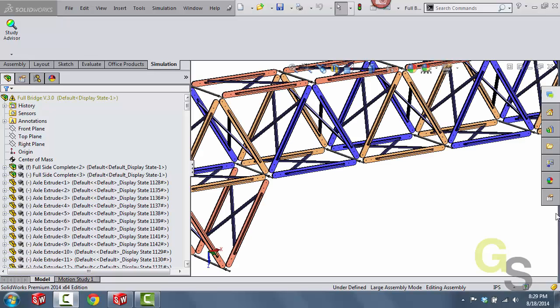The next thing that I'm going to do is create this simulation. Now normally what I like to do is make sure that I have 3, maybe 4 bodies max when I create my first simulation when I'm in the crawl phase. And I do that when I have shells and solids. Now because we're working with beams, it's a slightly different case.